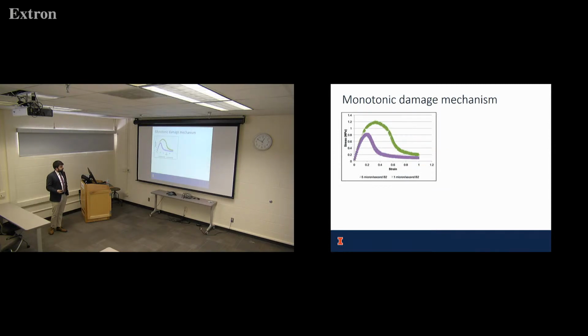So this is the stress strain curve measured in this test at two different loading rates. You see 1 micron per second and 5 microns per second. Typically we see higher strength for higher loading rate, which is interesting because for cracking resistance, we often think lower loading rate will lead to better cracking resistance. Not always the case. Maybe not the case, because we see higher strength here.